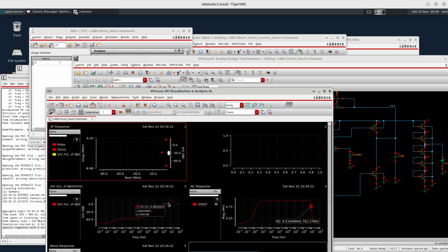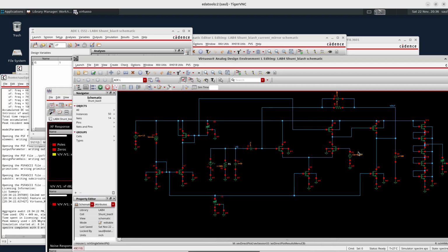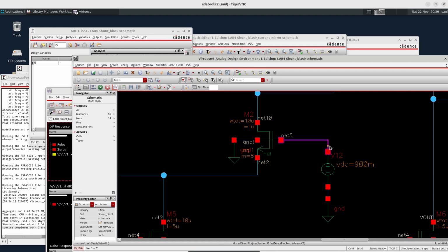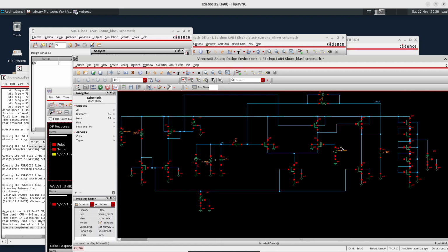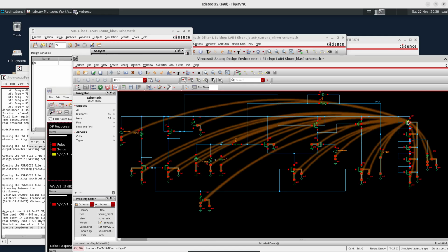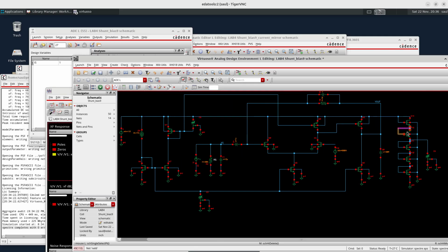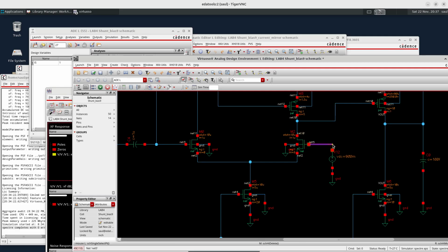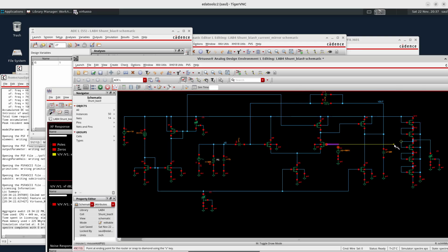So now we're going to do very quickly a demonstration of what happens if we don't use a band gap reference or control voltage from another part of the circuit. We're going to use these diode connected transistors here, this row of transistors, to generate the voltage, and then we're just going to tap this one here.